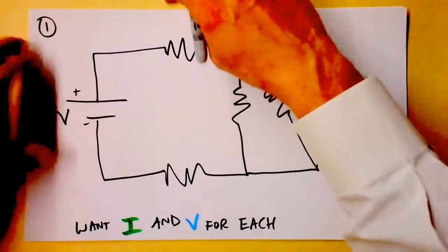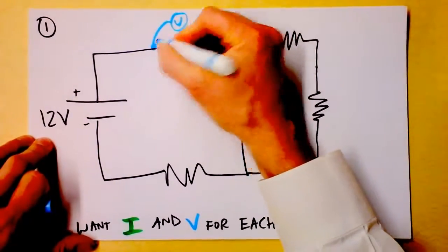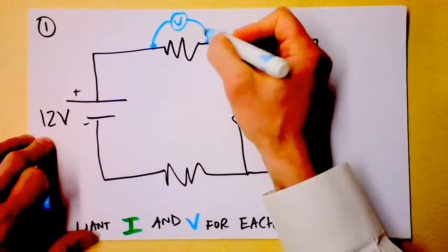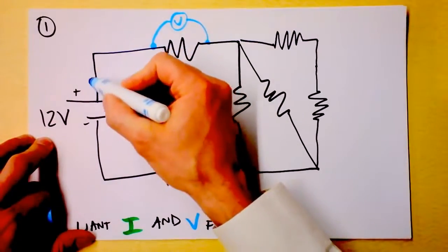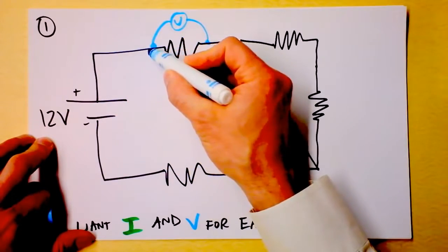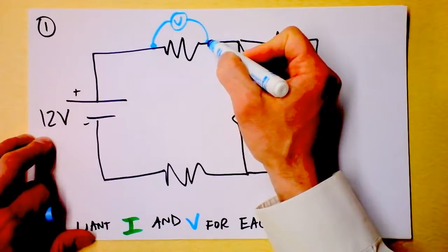Voltmeters would come on here like this. I'll just draw you a voltmeter. Here's the voltmeter that comes on here, and you would connect like that. Because see, an ideal voltmeter has infinite resistance and no current. Given the choice, the current's coming out here. The current's like, oh, I see infinite resistance or some finite resistance. It chooses to go through the resistor.